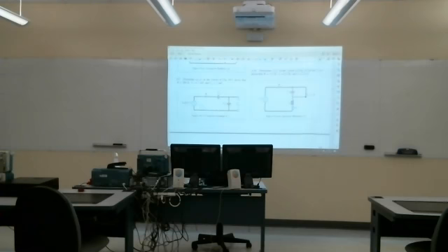here's our input called VI, and our output in this case is the voltage across this capacitor. I'll call it VO. The voltage could be current, or voltage across some other device, in which case the transfer function would be different. And then the capacitance C1 is 1 millifarad, so the impedance is 1 over SC. So 1 over a milli would be 1,000 over S. And then this is 5 times larger, so the impedance would be 5 times smaller.